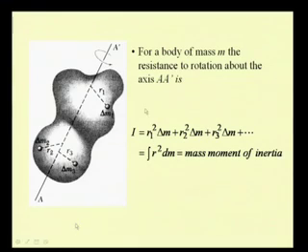So, we write I, the second moment of this mass about this axis a prime, as summation of the second moments of the various constituent particles, that is r1 square delta m plus r2 square delta m plus r3 square delta m, etc. So, in the limit this becomes dm, and this is the integration over this complete volume.